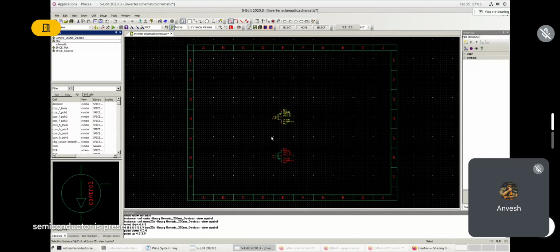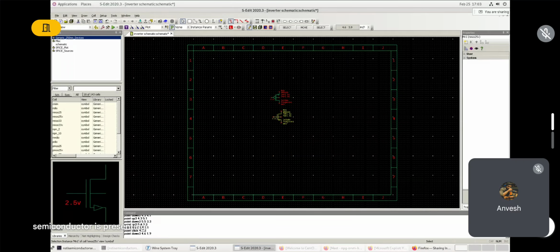So now I will just place it above. And for moving this one, you can use the mouse center button. Just hold it and you have to click on this. After clicking on this, yellow color will appear and click the mouse center button and you can move it. Or else even you can use control. You can click on this control and you can move this. If you hold on control and then you can use this. So not control, alt. Either alt or here mouse center button.